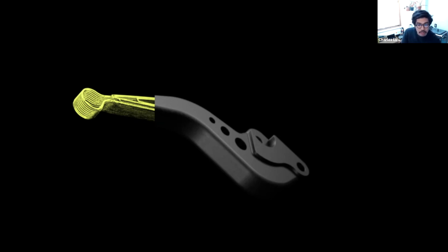What binder to use for the fiber strand? It is a nylon, so we're using the same material, a thermoplastic nylon, such that it can bond to the other material. If we were to use an incompatible polymer, then you would see delamination between the shell and the material and the fibers itself. So we use the same base nylon.